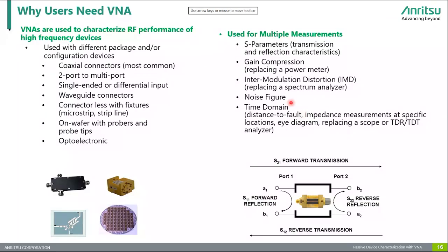And the noise figure measurements and time domain analysis, which includes distance to fault testing, impedance profiling, and even eye diagram analysis also. This makes the VNA a multifunctional instrument capable of replacing several standalone tools in a lab or production setup.